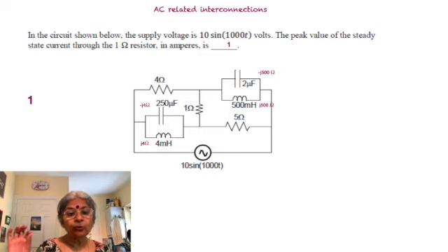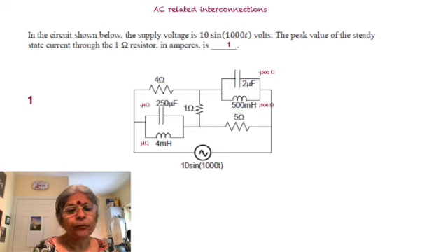So there are two open circuits, and the current released by the 10 sin 1000t flows through 4 ohms, flows through 1 ohm, and then the subsequent 5 ohms and returns. In other words, the total impedance, as is always true, is a simple value equal to 10. That is 4 plus 1 plus 5, which is 10. So 10 by 10 is equal to 1, which is the maximum, the amplitude of the sinusoidal current that's flowing through the resistive elements only. They don't flow through the inductive and the capacitive components.